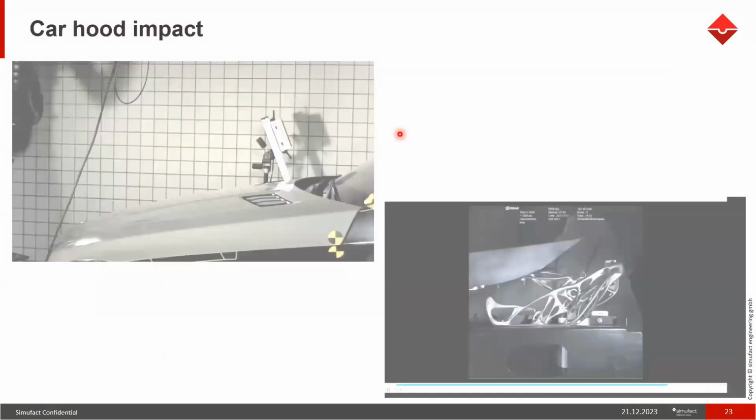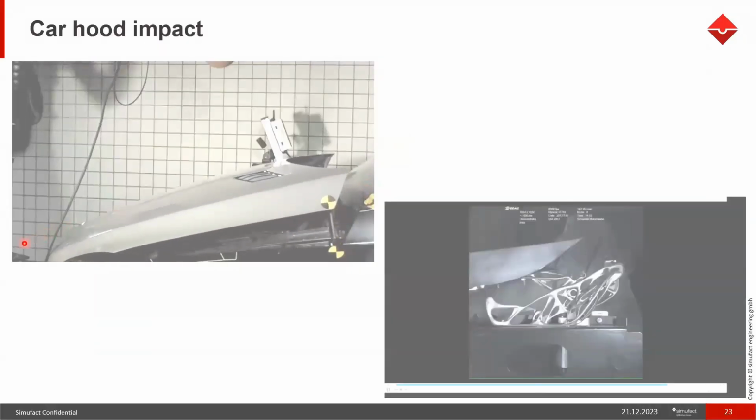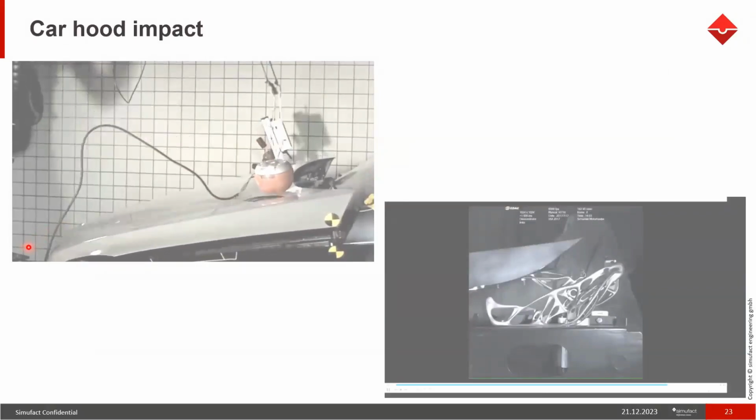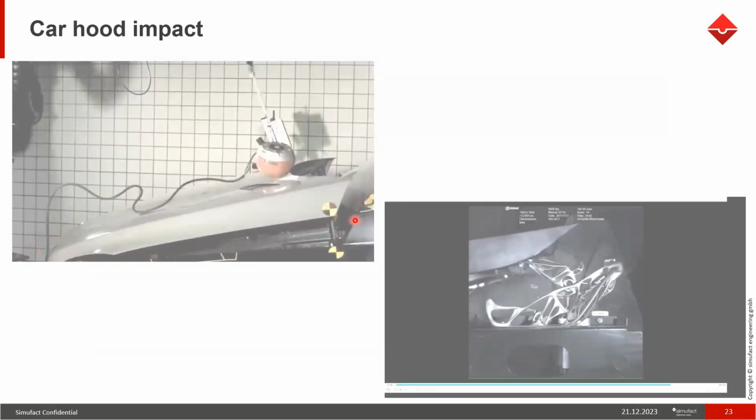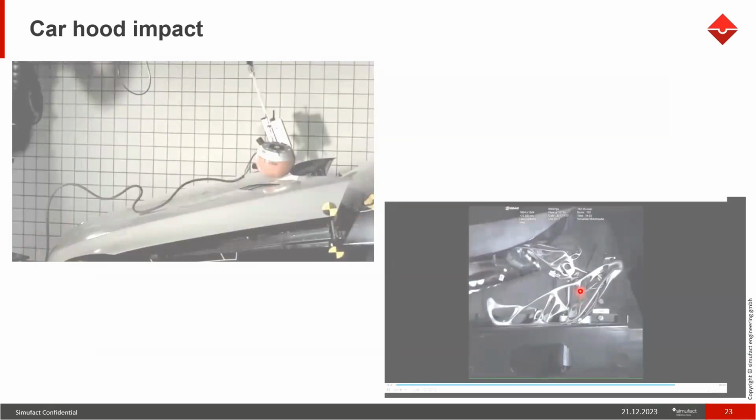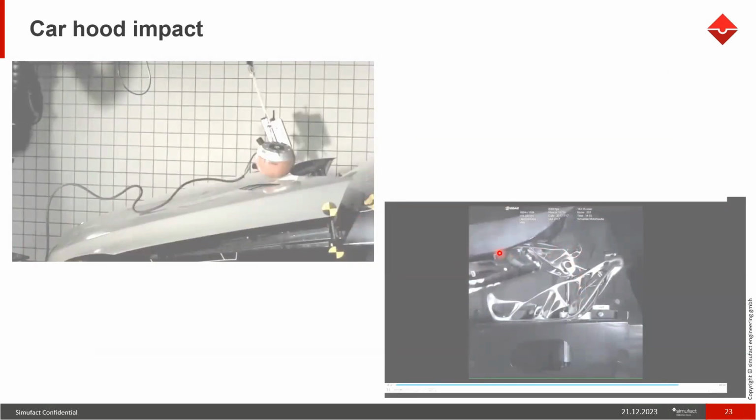So what will happen is, I think this video will show you. Suppose the pedestrian comes close to the car. What will happen is the sensors will activate this mechanism, the hood mechanism. So you can see the hood will get engaged and the hood will release so that the hood will be at a particular location. So what will happen is your impact, for example, there is a head impact over here. It will be much lesser compared to the hood when it is in the original position. So it can cause head injury to the pedestrian, which can cause damage to the pedestrian.